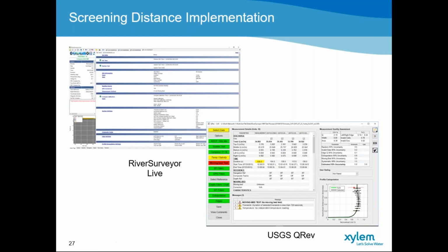So from the research itself, the facts: ADCP instruments with monostatic transducers send and receive the signal using the same transducer. So that's a fact, and we know that. We require a blanking distance to remove the ringing effect created because of the transmission of the signal through the transducers.